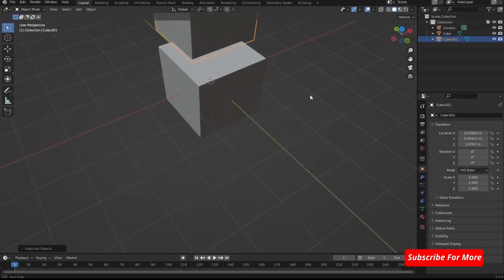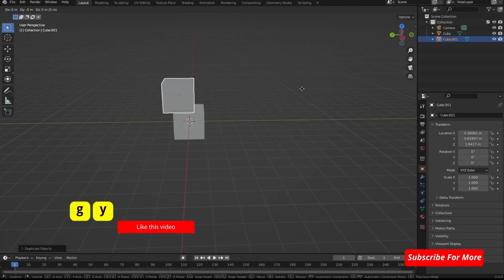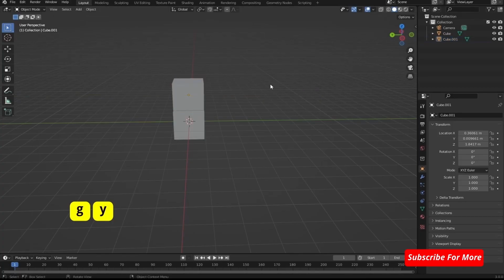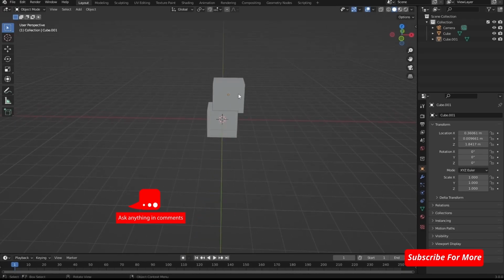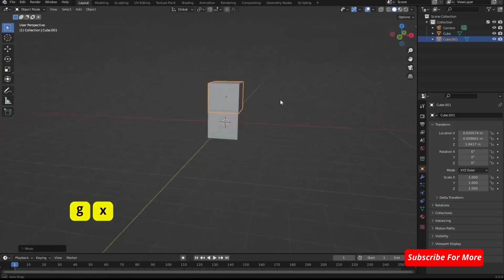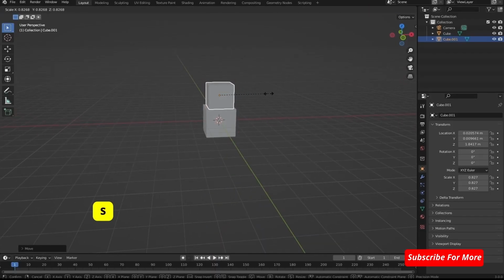Zoom in, move around, and G for grab, and move it on the Y axis. Press Y and move. We also have to move this on the X axis. Press G and then X. Now scale it. Press S and scale it to make it small.